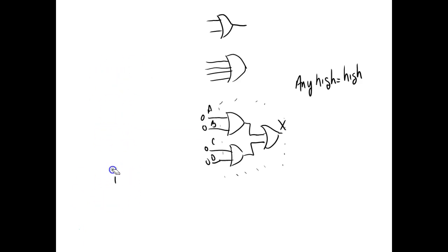I'm gonna have to move this up to the top, guys. Raise 2 to the number of inputs. So how many inputs do I have here? 4. So 2 raised to the 4th power is 16. Right? You understand that? So that tells me the number of input combinations I'm going to have to come up with on my truth table.